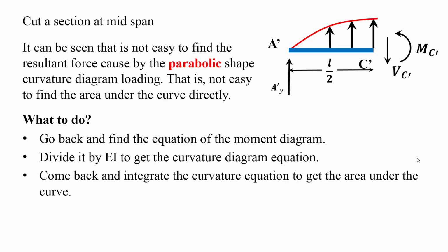Come back and integrate. Use integration because, again, integration is nothing but finding the load under the curve, or finding the area under the curve. And the area here represents the summation of the load or the concentration of this parabolic load. Then you basically continue the problem. So your only obstacle here is to find a concentrated force that can be represented by this segment. If you know how to do it using integration, you're done.